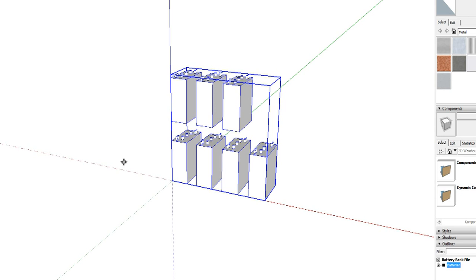And that's very simply done. Just put your circles on your sketch and extrude around the circles. So that's what we're going to do to start off with. And of course we want holes because we want nuts and bolts holding this thing into place. So to start off with, I'm going to get my tape measure out. I'm going to measure 100 along and then 50 this way.